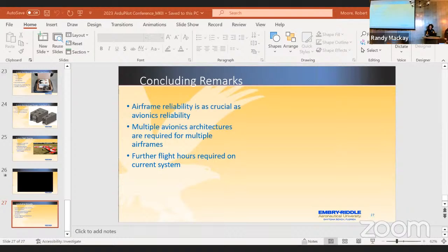This redundancy, does it work in the master-slave mode? I just wanted to know how the handshaking is done between the two flight controllers. In the current setup, the second one would be in standby mode. Basically, it would be sitting in standby mode, and you would say this one's in charge. That's step one. Well, that's only for the multi-rotor code. The plane code has a different set of issues; there are differences between the multi-rotor and the plane.